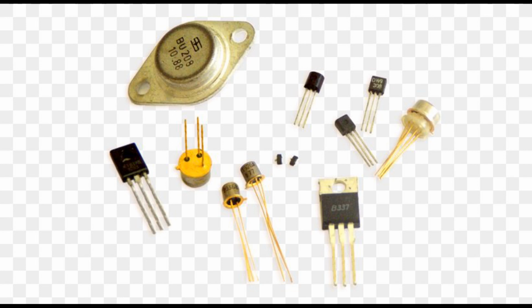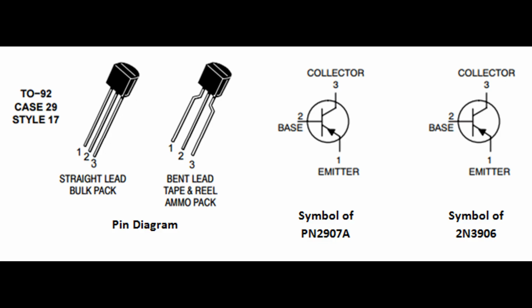Hole mobility. In P-type materials, the majority charge carriers are these positively charged holes. When an electric field is applied, the holes move toward the negatively charged side, which is typically the cathode or the collector in a semiconductor device. Conduction. P-type materials have relatively low electron concentrations compared to intrinsic or N-type materials, but they have a higher concentration of holes. This means that P-type materials conduct electricity primarily through the movement of holes, resulting in a net positive